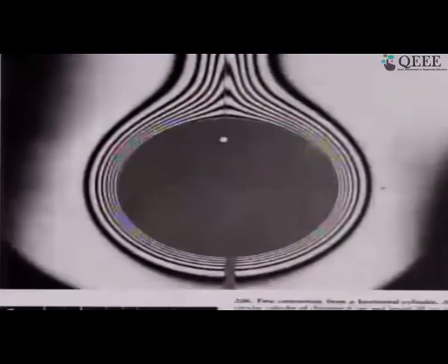So this is telling us a lot about what is happening to heat transfer from the cylinder. The local heat transfer coefficient will be highest somewhere in this range, about 90 degrees or thereabout. It is slightly less, by maybe about 20%, 30%, at the bottom point, and it will be very poor, considerably poor, at the top point. So there's a big variation of the local heat transfer coefficient along the direction, starting from the bottom.